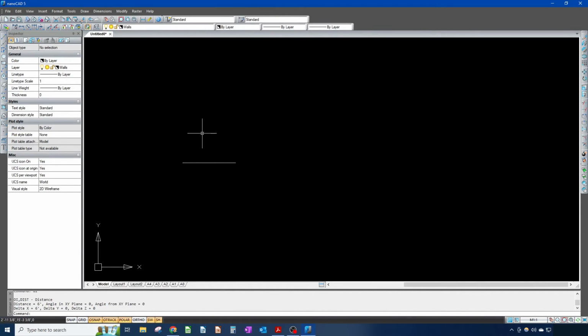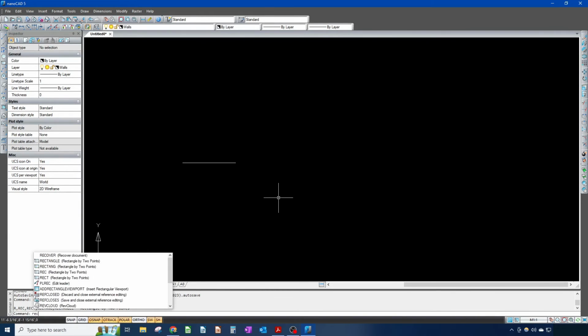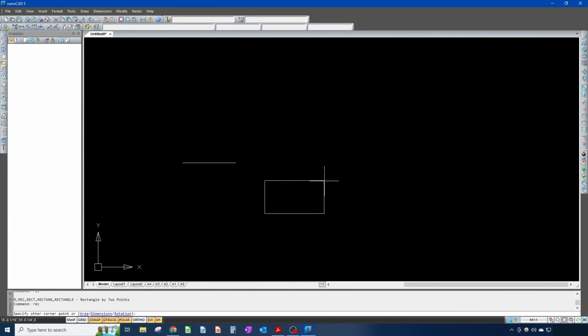I have noticed that sometimes I have issues with that, especially when making a rectangle, where you have to specify a different corner or the opposing corner. So let me try that with a rectangle now. Specify first corner. Typically, if it's a linear distance, then you don't have to put the @ symbol. However, whenever you have 2 different corners, like in this rectangle, whenever you have Cartesian coordinates, which is what the rectangle kind of follows, you have to put the @ symbol first.